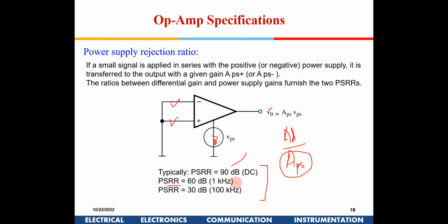Typically, sir, why will there be gain due to power supply? Actually, when the power supply changes, the output should be stable, but it won't, because the biasing conditions of the transistors will change in all practical circuits a little bit. So it will result in a small output change. Is it related to the VDD variation that we have seen? Yes, power supply is VDD variation only.